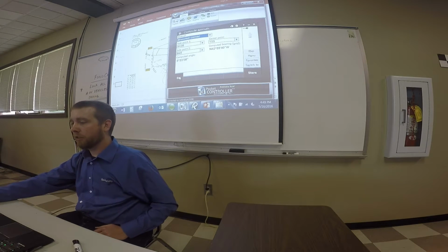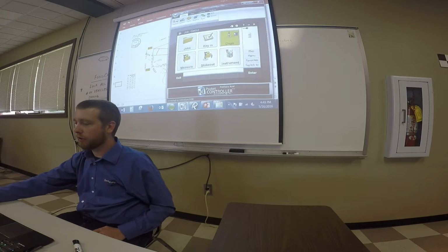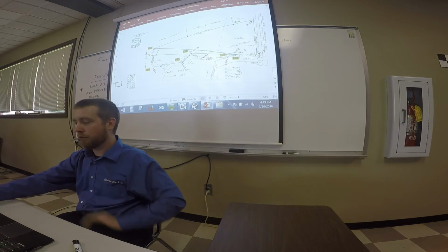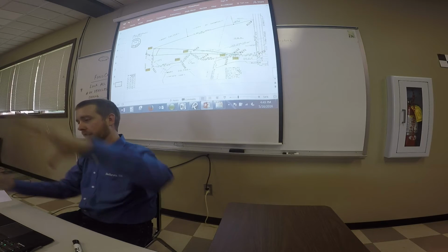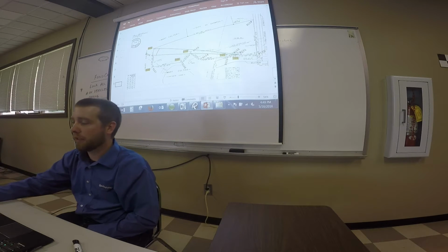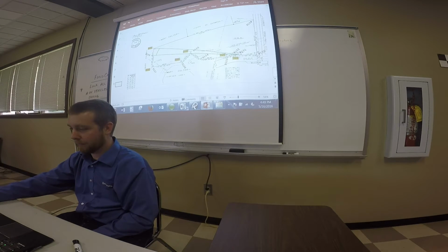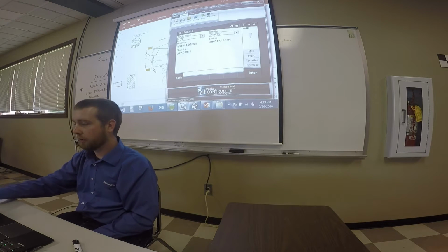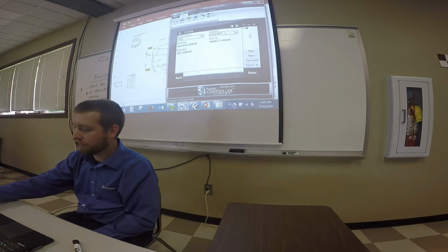Okay, so you want to escape out of there, go to COGO, transformations, this time we'll rotate. Our origin point is going to be the point we want to stay still, where everything else rotates around. And that's going to be number 103 down here. And then we'll punch in our rotation angle that we just found out.